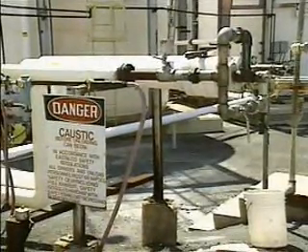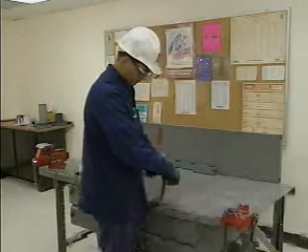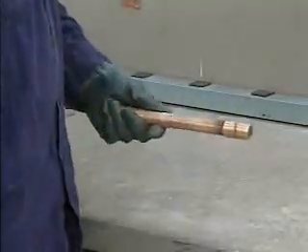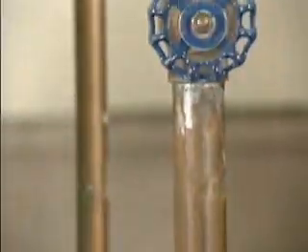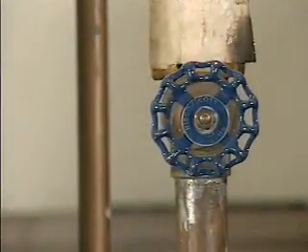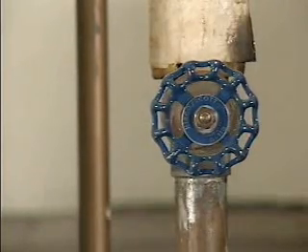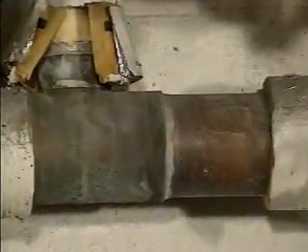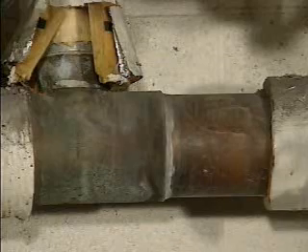When copper ages, it becomes dark and dull and can be easily confused with other types of pipe. Polish a small area of the pipe to bring back the original color if you're unsure of its material. Copper pipes naturally resist rust that could contaminate the air. For this reason, they're often used in pneumatic systems such as conveyors, mills, pneumatic valves, and control valves. Though it works well in most environments and is strong enough to handle loads that might rupture a plastic pipe, copper pipe is best suited for use in systems in which temperature and pressures are not extreme.